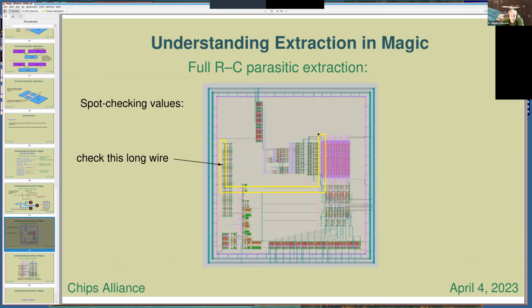So obviously this is a set of code that somebody wrote a long time ago, and I've been trying to figure out, is it still valid? So I've been running the full RC extraction. This is the SRAM, well, one of the SRAMs. This isn't the 1K SRAM, but Matt Goodhouse sent me this little tiny SRAM, which has just, I don't know, like an 8x8 set of cells. And it's small enough that I can extract the thing in a few seconds. So it's fairly easy to work with and doesn't take all day to do extractions.